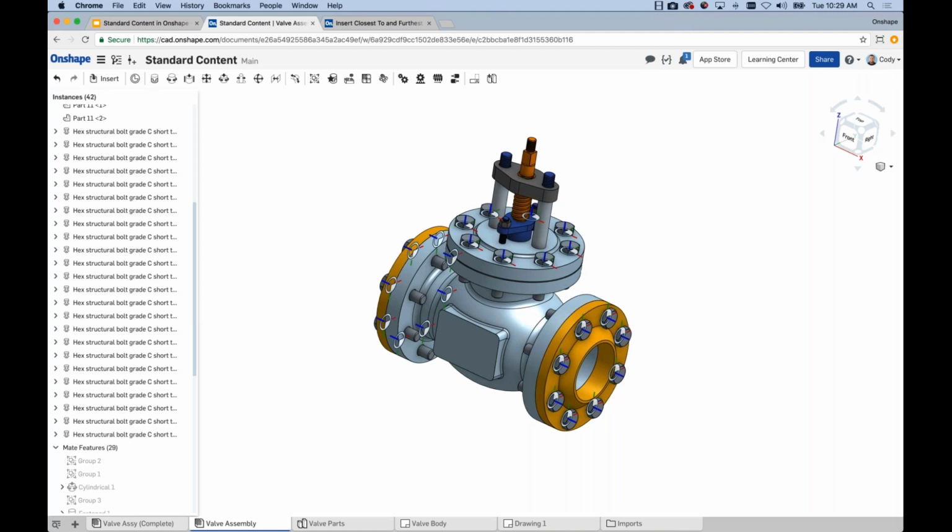I found it difficult to insert a flathead screw into a countersunk hole. Forgive me, I'll have to try an example of that. It may be a scenario where the mate connection points that are automatically determined aren't ideal. And you can edit the mate and shift things around using a normal, offsets and things if you run into that.